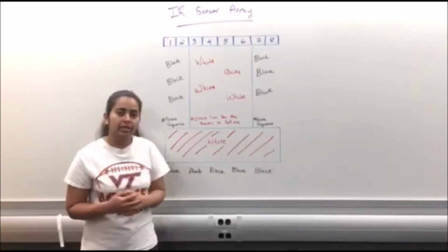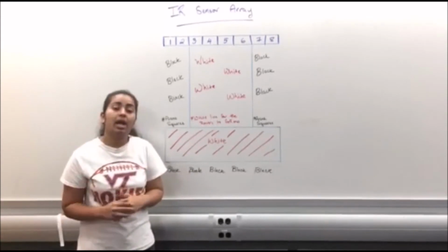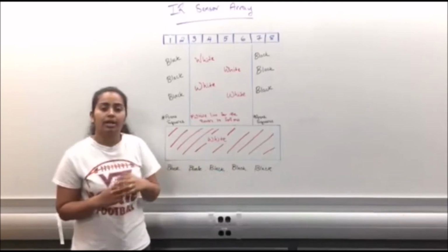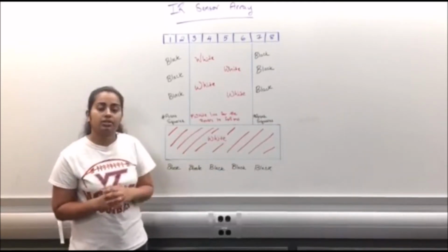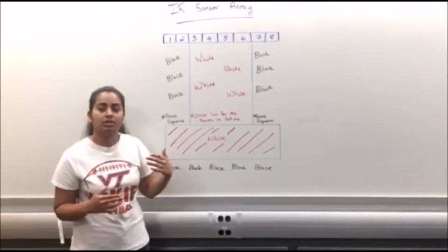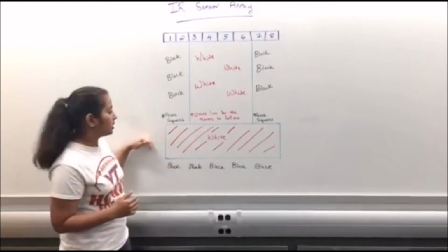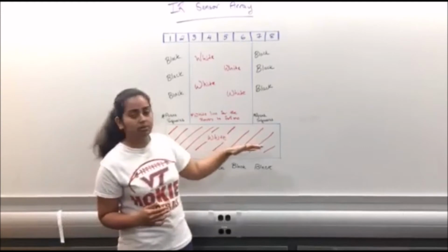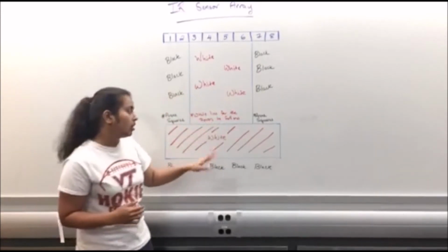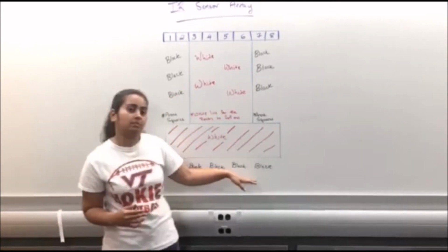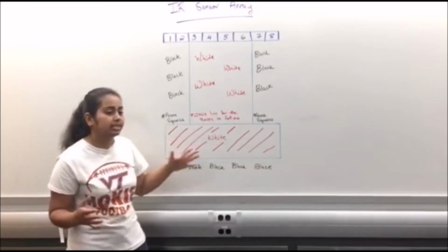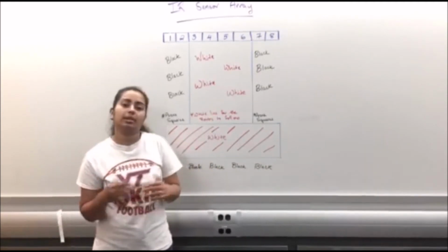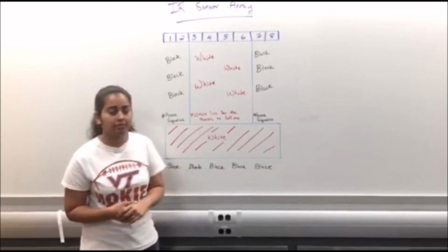So the sensor thread gives commands to the motor thread and asks for help from the server. The sensor thread sends for help to the server only if it's at an intersection, where it sees all white, so all 8 sensors are seeing white, or if all 8 sensors are seeing black. If it's all white, then it's considered an intersection. If it's all black, it's an error state, and it's asking for help to get back on the line.